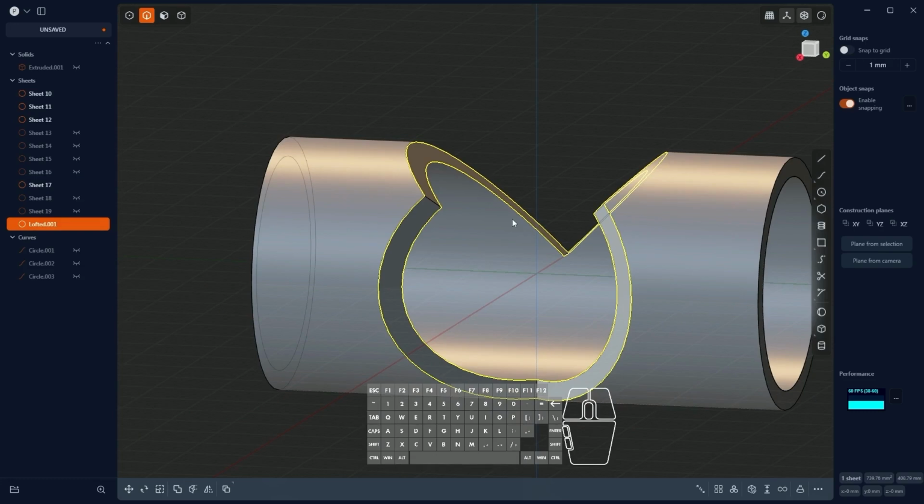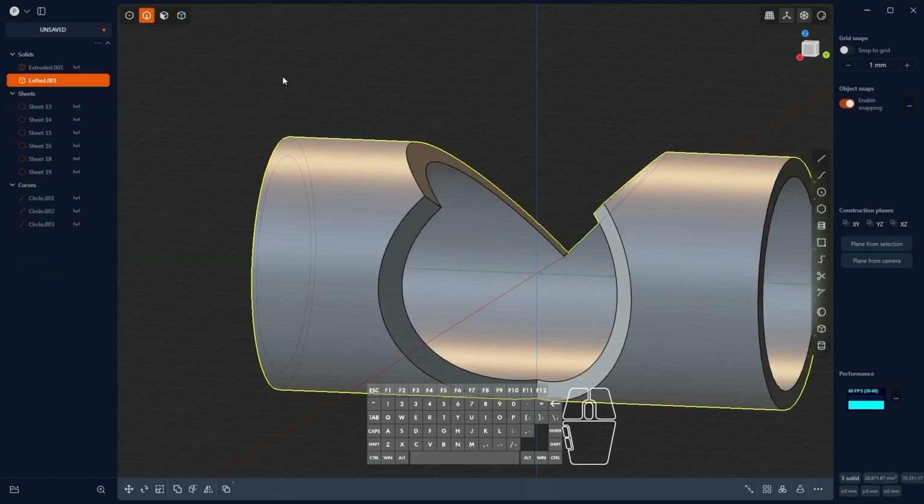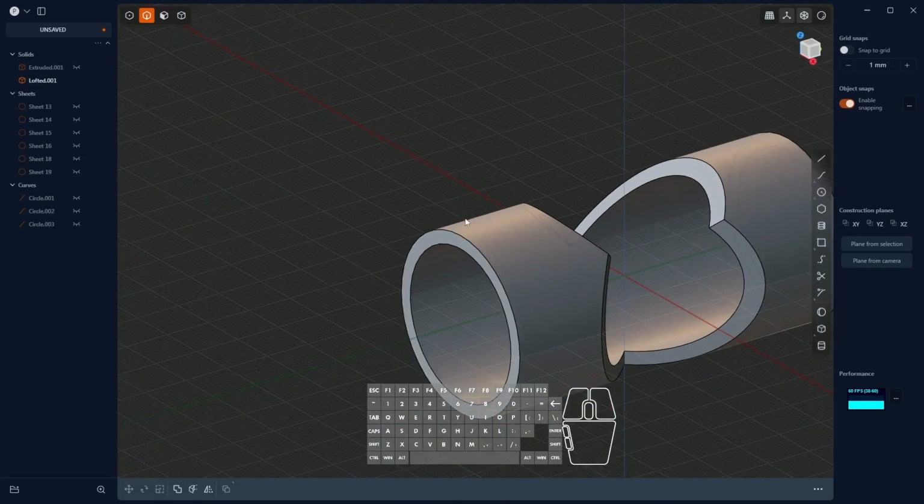At this moment they are surfaces. If we would like to create a solid from this, select all the surfaces that make up this solid with the Ctrl key pressed and press J on the keyboard to activate the join command. And this allows us to create a solid. And now we have created a solid this way, and we proceed similarly with the remaining elements.